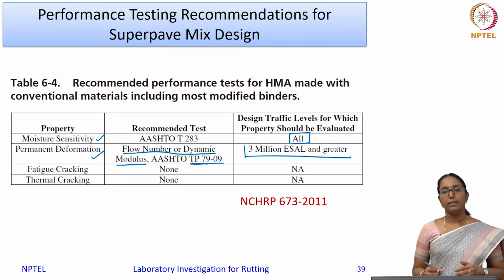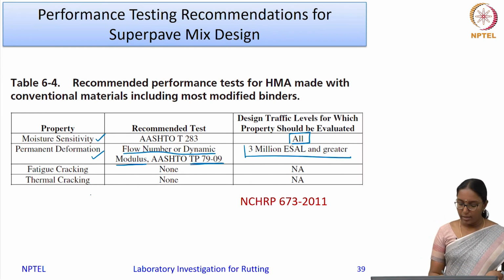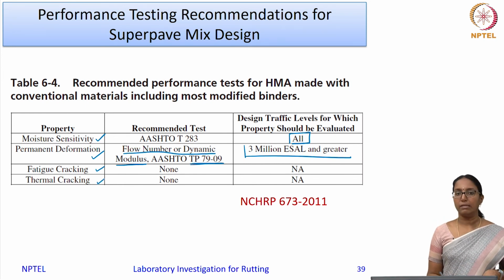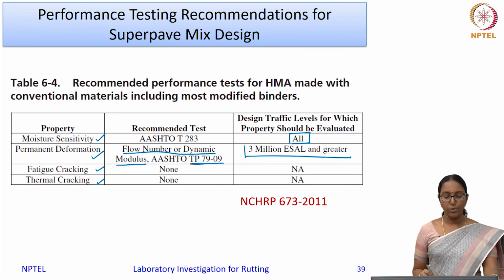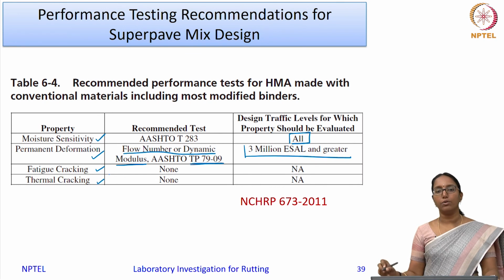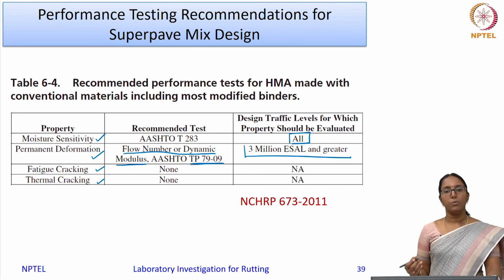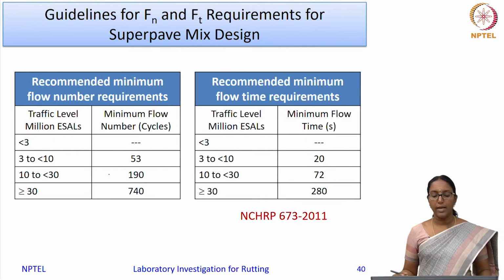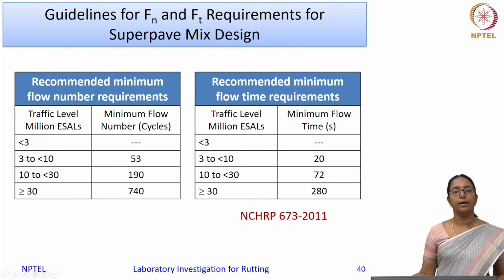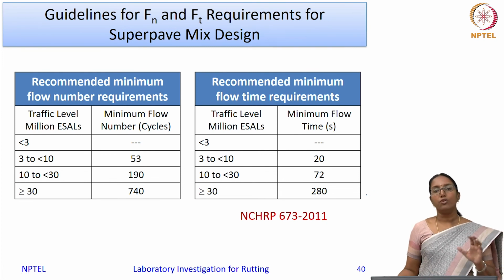But the protocol does not necessarily recommend the fatigue cracking test or thermal cracking test. You need not do these two tests, but what is necessary is that you have to conduct the moisture sensitivity test and the permanent deformation that has to be established using a flow number test, or you can go for a dynamic modulus test. The dynamic modulus test we have discussed in some other lecture. And these were the recommendations that are given so that you can use this mix in the field.